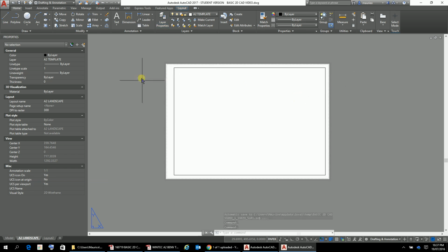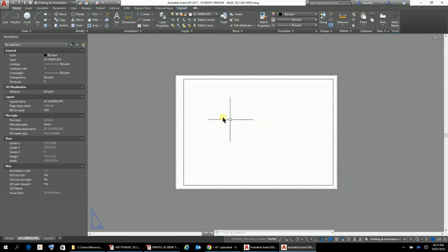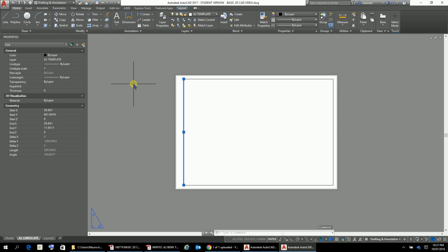And that now means that the line weight for that little outside one there will be 0.25, but you can see here it's set by layer. I can always, if I wanted to for an individual line, override it, but let's try to keep it by layer. Alright, so that's got the outside all done now according to how we want it.